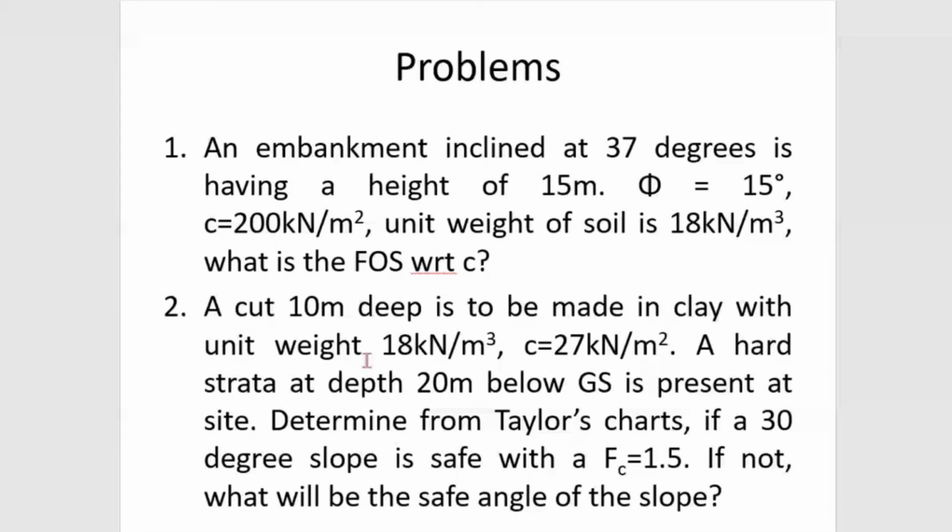Take down the question. Okay. First thing, draw a rough figure and figure out your depth factor. If you need to draw a rough figure, you can draw that. How much is my depth factor here? What is the equation for depth factor? df is equal to, so what is the d here? 20 meters, right? And h is 10 meter, yeah, cut 10 meter deep. So how much is my df? 2, correct.